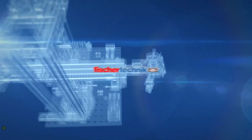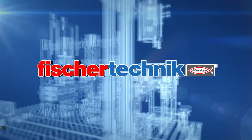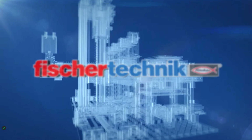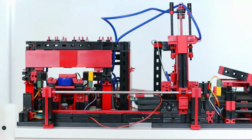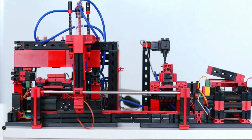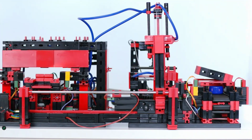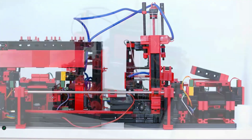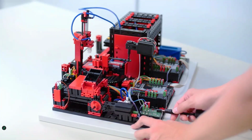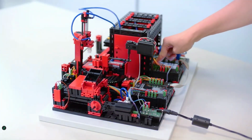So what you're going to see here is a furnace simulation with a pneumatic sliding door. Essentially, it's a downstream processing station with a pneumatic transfer unit that includes a vacuum gripper. It has a cutter with a rotary table, a simulated cutter, and a conveyor belt. Components you'll find on this model include four mini motors, six push-button limit switches, two photo transistors, two LED light barriers, four solenoid valves, and a compressor.